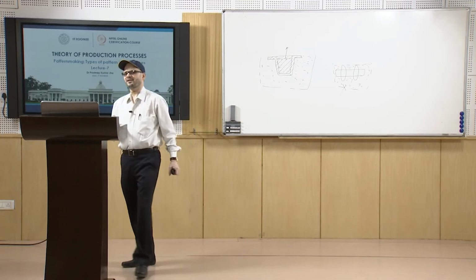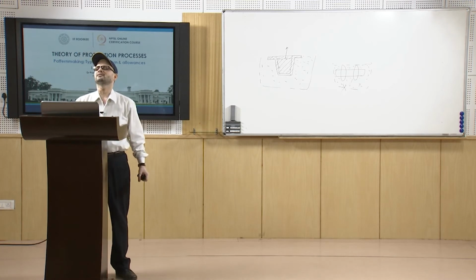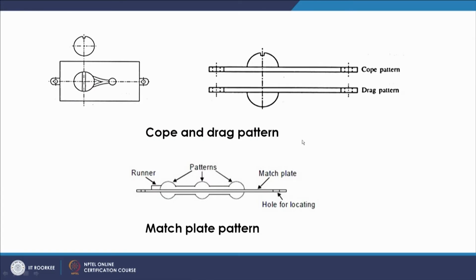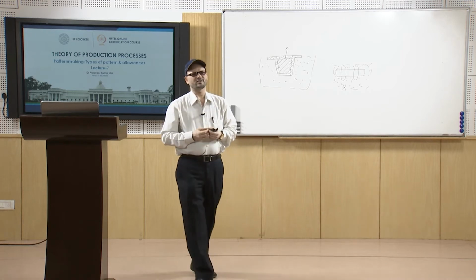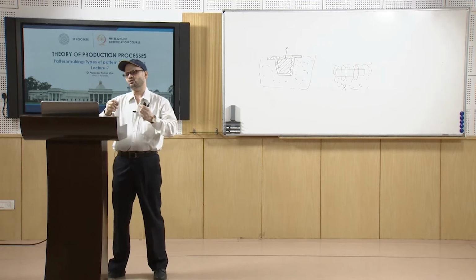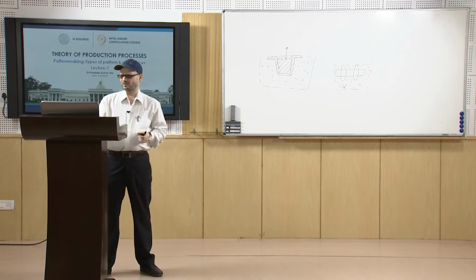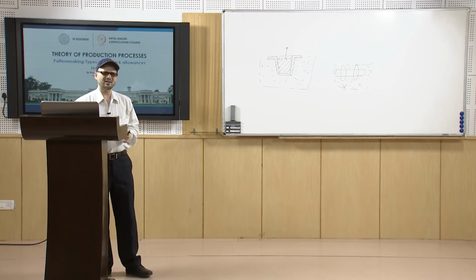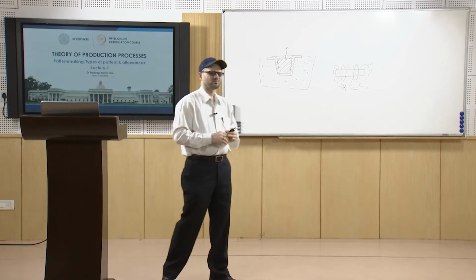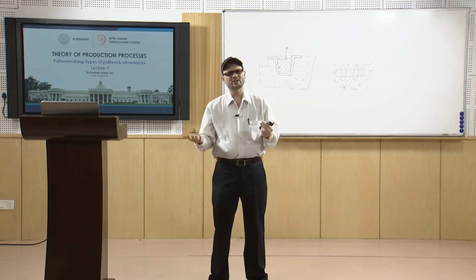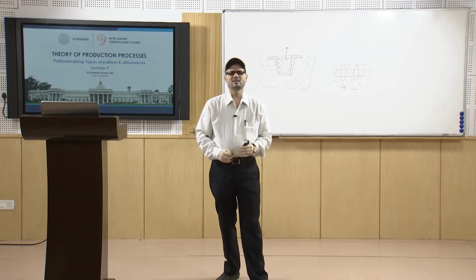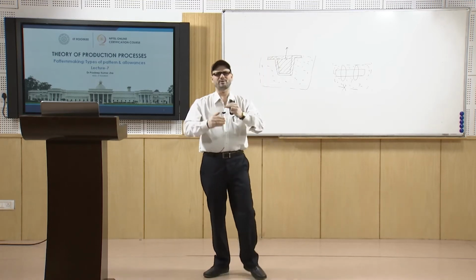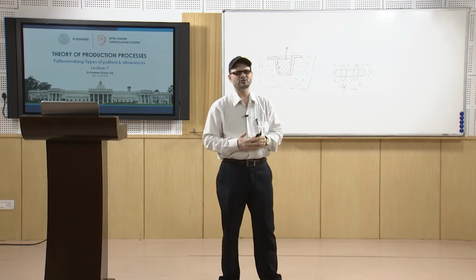The thing is that here we are using the cope pattern and the drag pattern individually by using the pattern plates, because in this case you have the flexibility to go for a little higher mass or little higher weight. So that way you have two different patterns. But on the other hand, you have this match plate pattern. Rather than taking the cope pattern portion out, then putting another plate and making the pattern for the drag portion further,